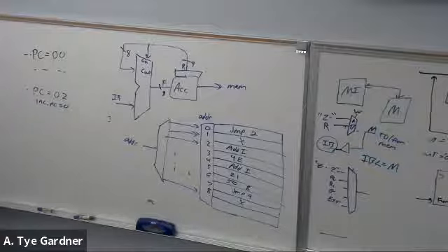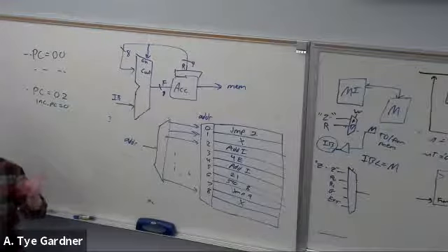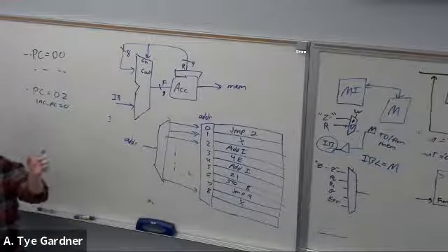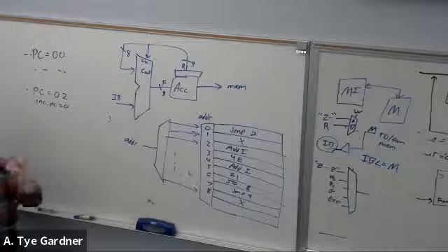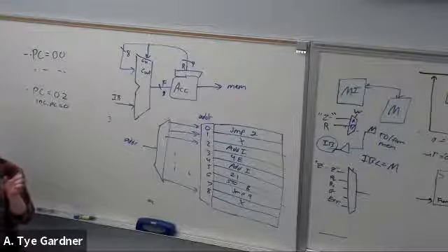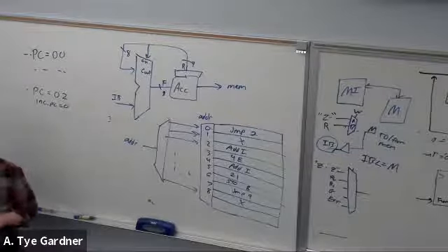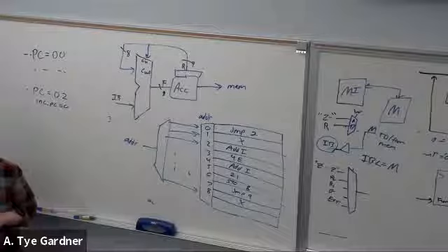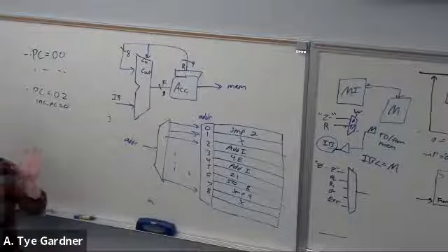So the MAR just stores the most recent value that you have, correct? Yes, whenever the last time that you asserted load MAR, whatever was on the internal bus will get stored in it, and then stay there until the next time you assert load MAR and have a rising edge of the clock cycle. So when you assert load MAR a second time, what happens to that address that's previously in there? It just disappears. It's gone.